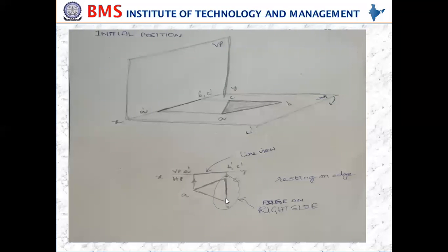So first you need to start with the BC. And then take the length of 30 mm from B, draw an arc to get the A, and from C also draw an arc and then cut both, and then you're going to get the A. So that equilateral triangle is going to be joined.